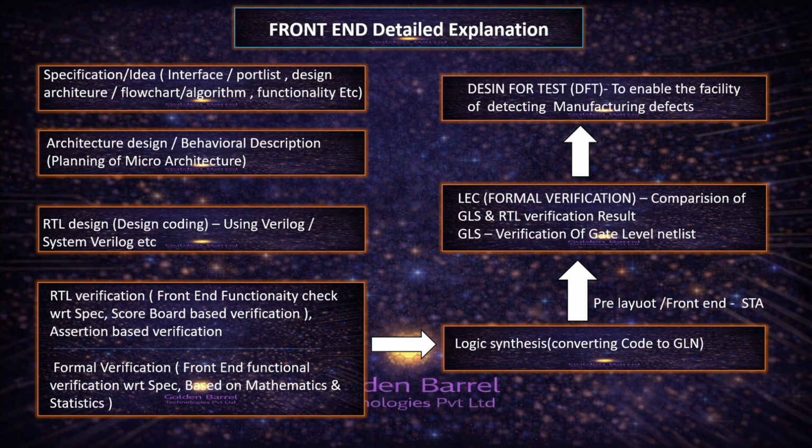Right. Now what is meant by synthesis? There is HLS, high level synthesis. There is logic synthesis. But now this is about logic synthesis. What is meant by logic synthesis? Now here our code is in code format only. This is a verified design code. This verified design code will be converted into a gate level netlist, and that is called logic synthesis.